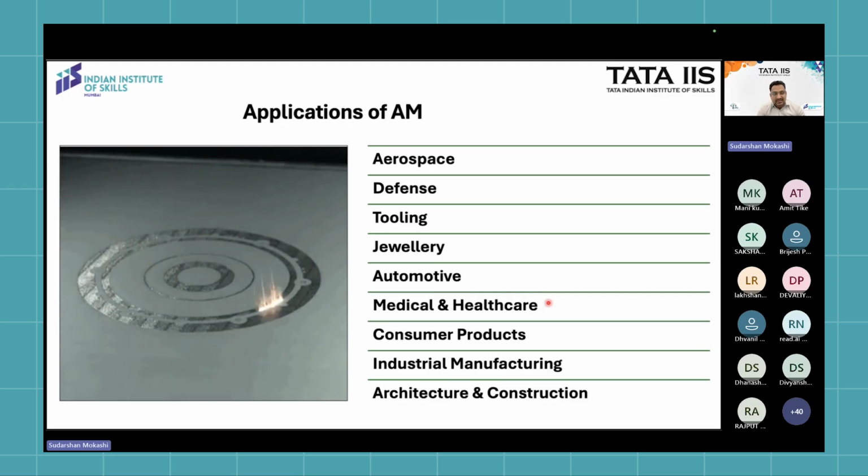So we also reduce the cycle time with the help of cooling channels. In jewelry, SLA 3D printing is used; we have a castable resin material where we can create the jewelry models in that printer, and we can easily cast in gold.